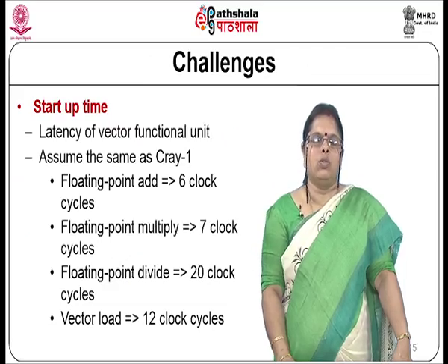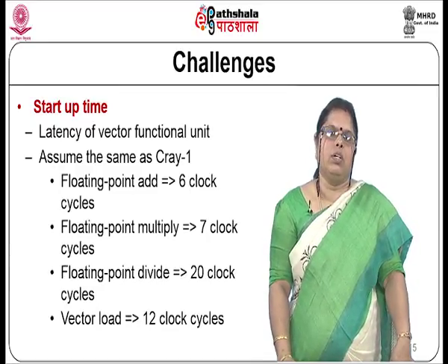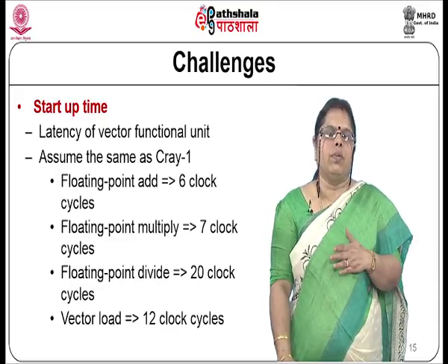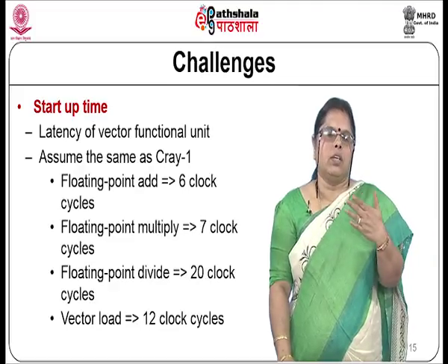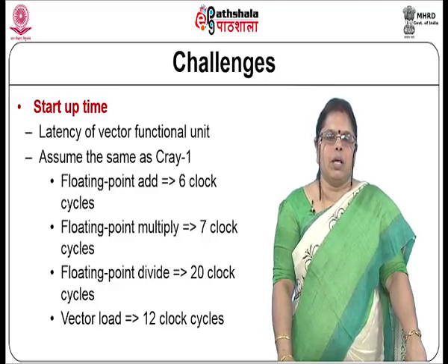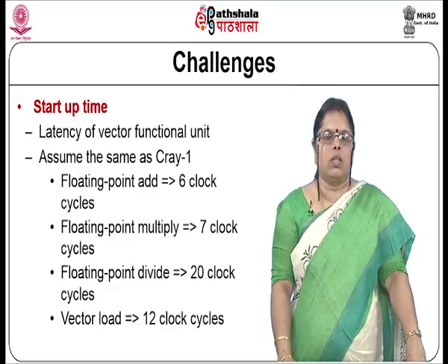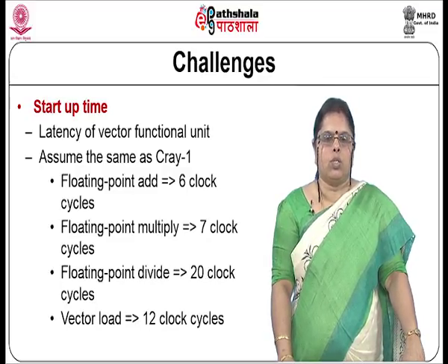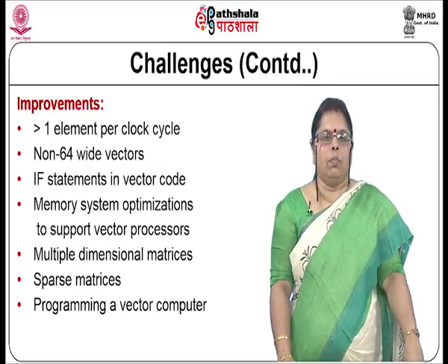Among the challenges associated with vector architectures, startup time is one of the issues we have to look at, because it depends on the latency of the vector functional unit. Only when the pipeline becomes filled up does it start delivering results at the other end. So, you have to worry about startup time. If you assume the same startup times as the Cray 1, a floating point add takes 6 clock cycles, multiply 7, divide 20, and vector load 12 clock cycles. That depends upon the number of stages you have in your pipeline.